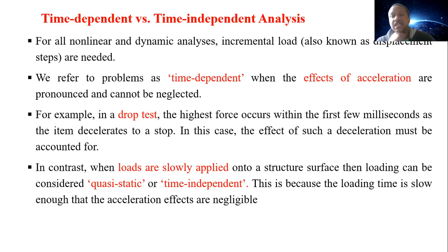In this case, the effect of such deceleration must be accounted for. In contrast, when loads are slowly applied onto a structure surface, the loading can be considered static or quasi-static, or time-independent. This is because the loading time is slow enough that acceleration effects are negligible.